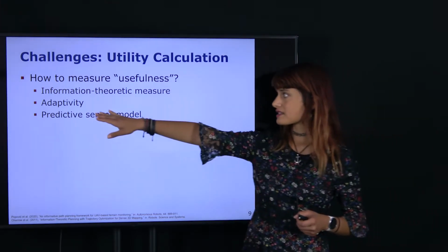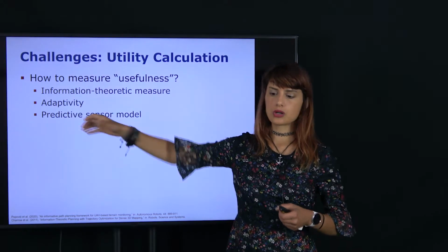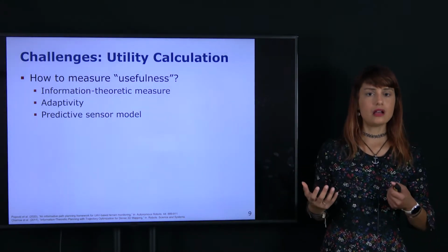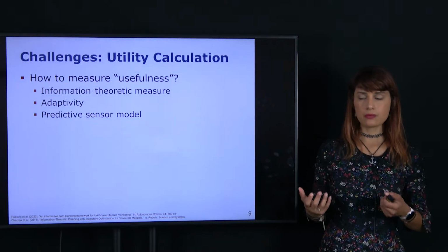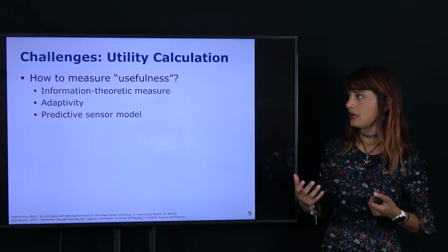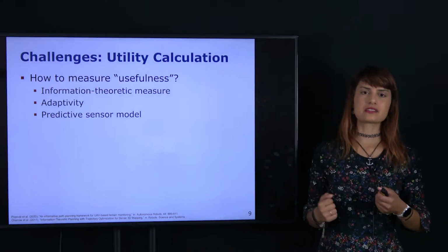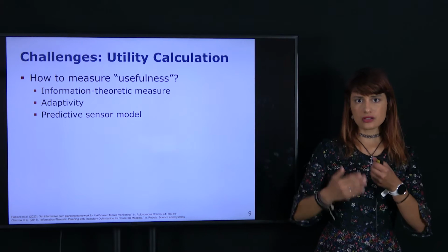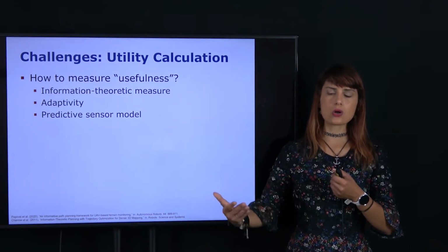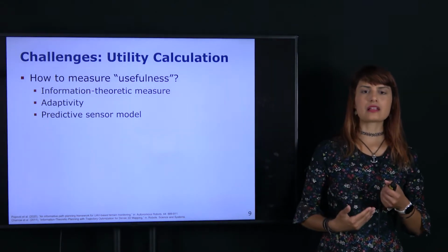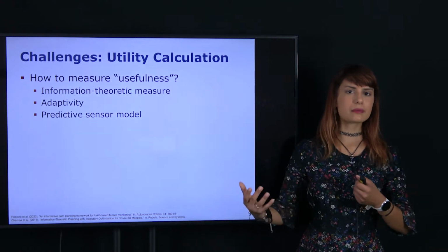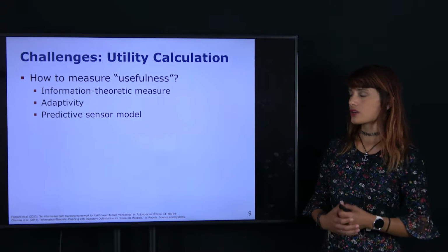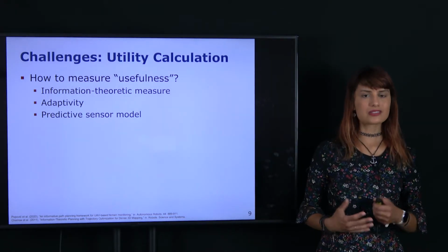In contrast, adaptivity allows the robot to see and analyze the measurements that it's getting with respect to the map by integrating them in the map, and then design next plans based on that current information. So the map is continuously updated online during the mission, and the plans are regenerated. So there is replanning happening online. So adaptivity is very attractive in many monitoring applications.